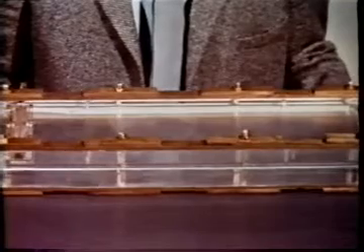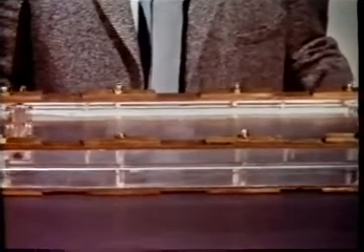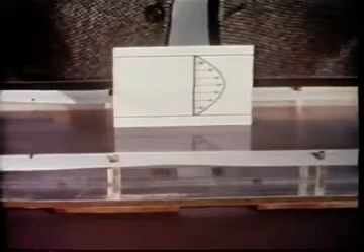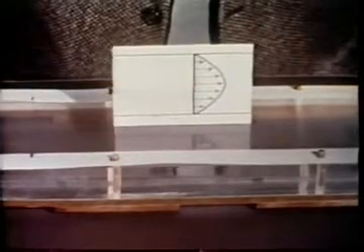When fluid is forced to flow through the cell, all particles in the same neighborhood are subjected to the same pressure gradient. The fluid velocity varies, being zero at each plate and a maximum midway between them. But at all points on a line perpendicular to the plates, they are moving in the same direction. In the Hele-Shaw apparatus, colored fluid is injected into the stream through a number of regularly spaced holes, and since the streamlines originating in any neighborhood remain close to one another, the lines of color remain sharp.